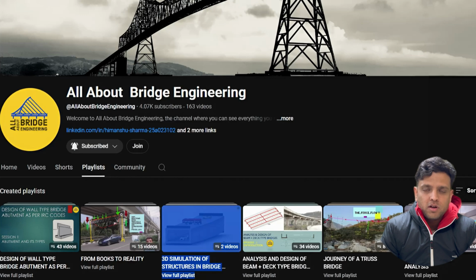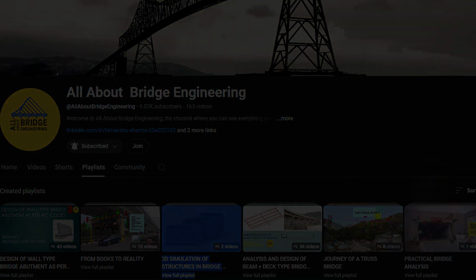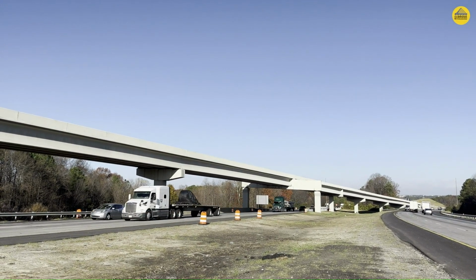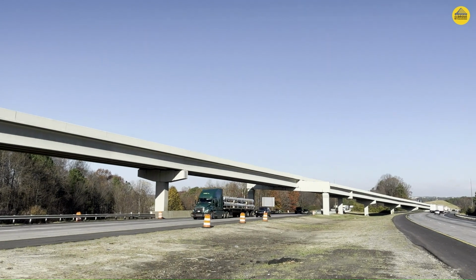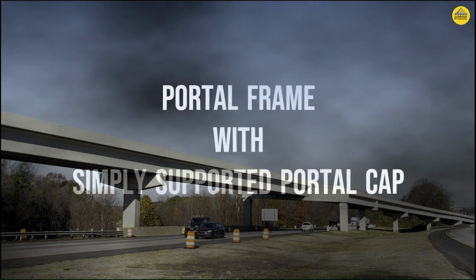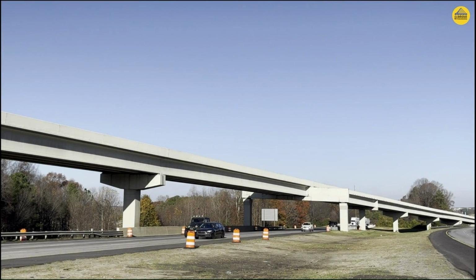In today's episode, we will try to correlate types of portal frames which we have studied in our structural analysis textbooks and see its practical applications in bridges around us. And accordingly, this episode is also put in the playlist From Books to Reality. The speciality of the structure that we have today is that the horizontal member of this portal frame is not monolithically built with the vertical members, but it is simply supported over the vertical members.